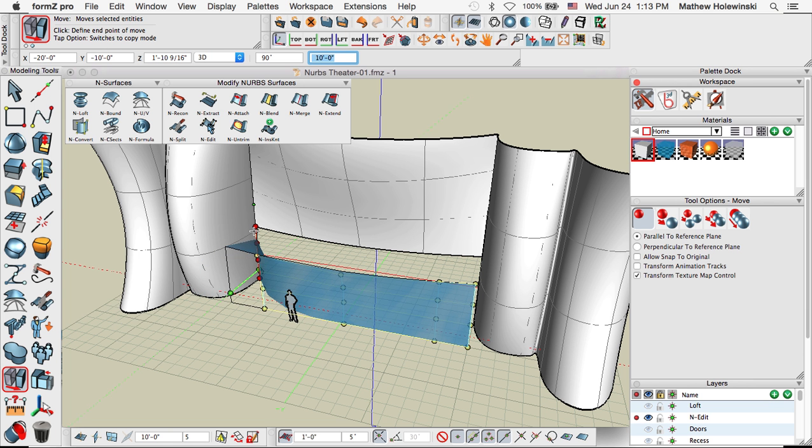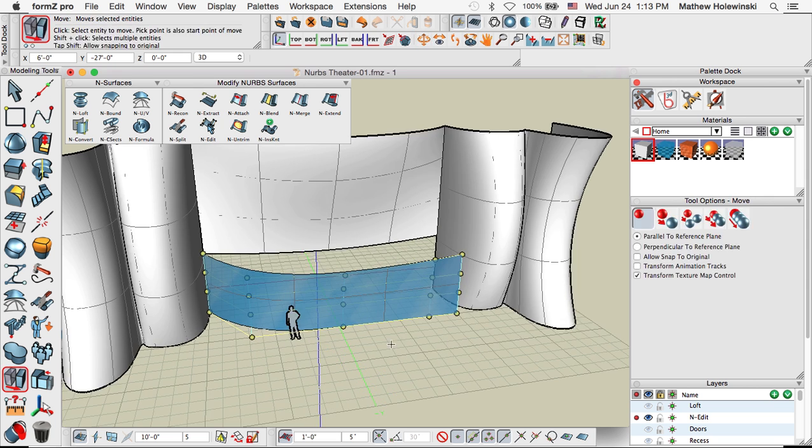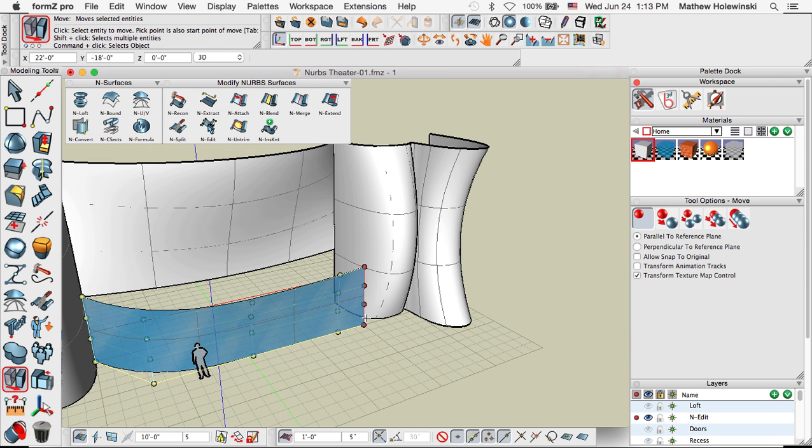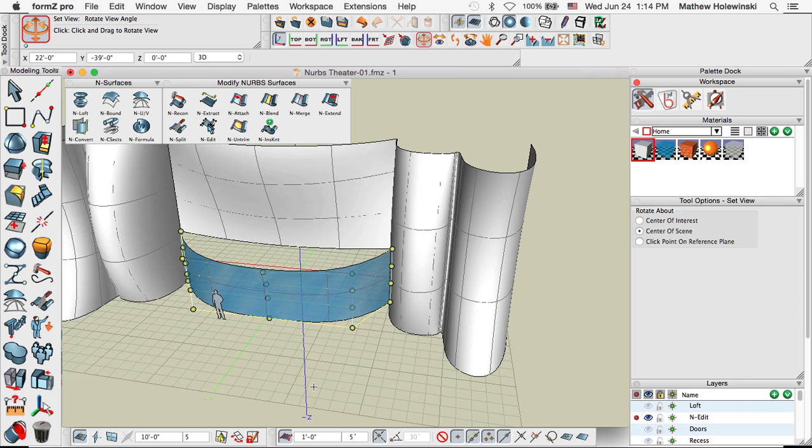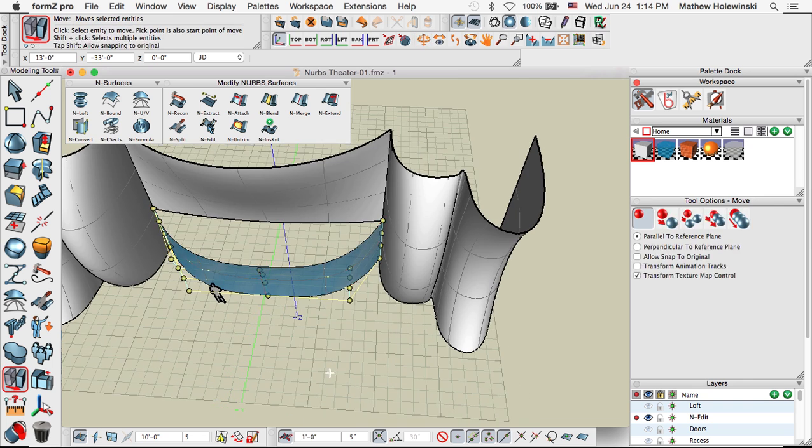So I can snap it back here, and I get that control line to snap perfectly back there. So let's grab this control line anywhere, move it along the guide, hold down shift, which locks it along that guide, snap it to the back corner point there, and everything lines up perfectly. Let's get a little more curvature in the front here.